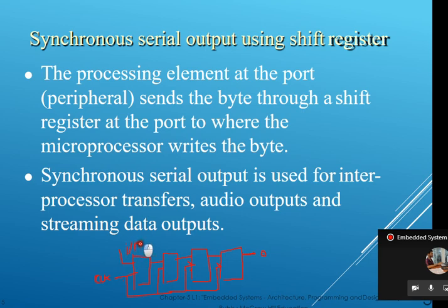So here what I am doing, I am going to give the first input. So totally a series of input, just consider 1, 0, 1, 1. Okay. After giving the first bit, the LSB is nothing but the first bit. I am giving the first one here. At that time the first clock pulse is given. So far no process has happened here, and during the second clock pulse, a D flip-flop reflects whatever input you give, it only acts as a buffer. So one clock pulse delay.